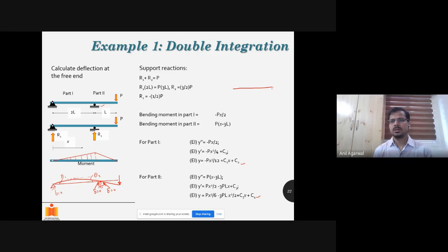So this is the beam. This is 2L length. And I'm applying a moment here, and a moment here, this way. So the deformed shape will look like this. This angle will typically be half of this angle. This will be θ1, this will be 2θ1. So a similar situation would arise here. θ2, if you actually calculate it in this particular case, will turn out to be twice as much as θ1. Even if you can't think of all this, there is no reason for you to assume that θ1 and θ2 are equal.